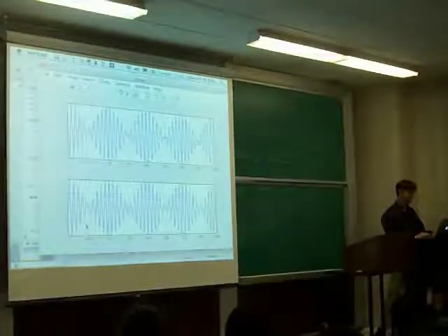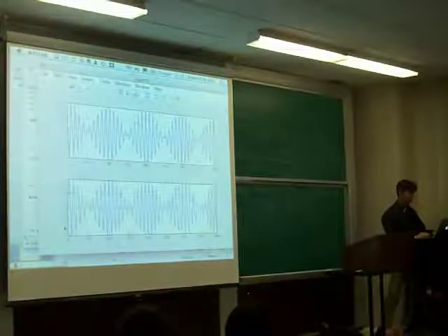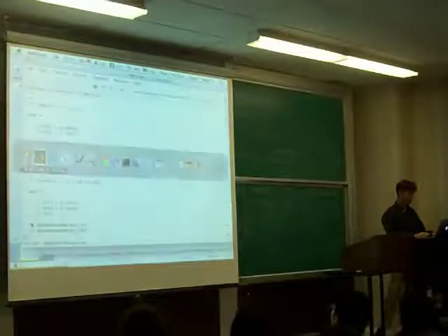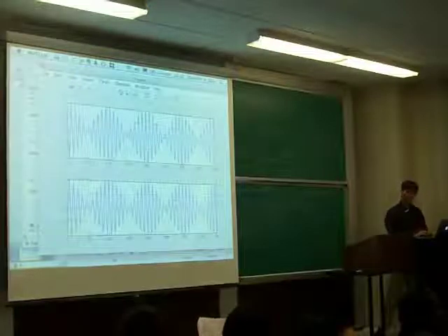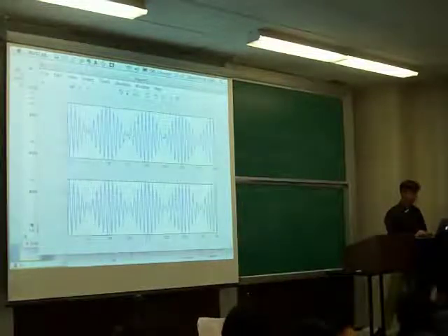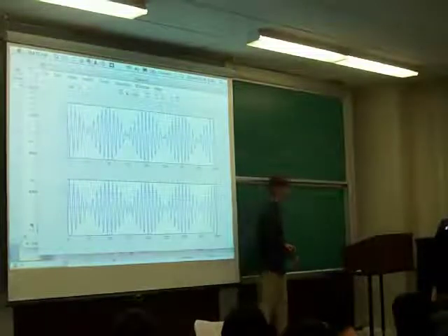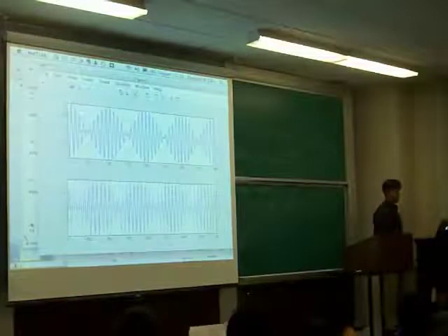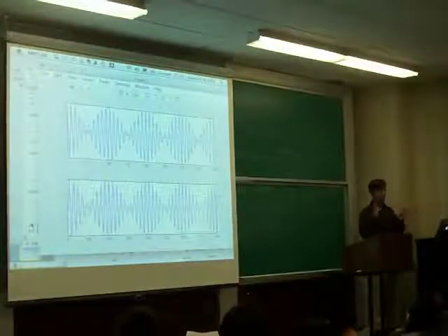So you can see that, okay, and that's the other one. Let's run that again. So what I'm going to do now is, you're going to see on the bottom curve the red line is moving, but the fine structure, the zero crossings of this blue line of the carrier, stays fixed. So this is a group delay without a phase delay. You see how the blue curve sort of scales up and down, but the red curve is moving.